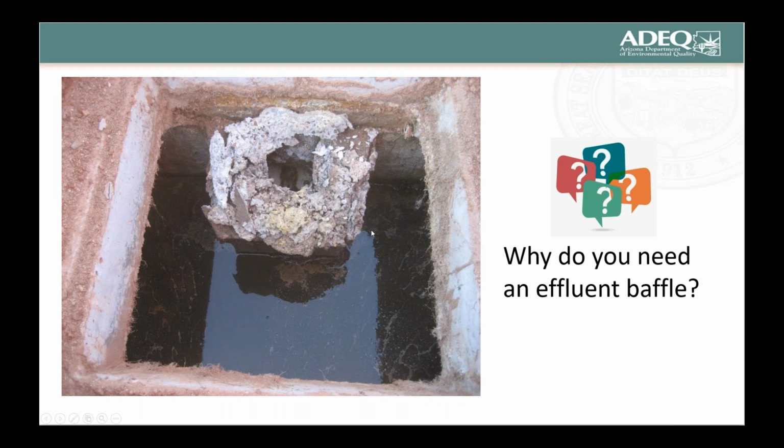All right, why do you need an effluent baffle? So here's a nice picture of a concrete effluent baffle that's being corroded and is breaking down. And so, of course, you have the baffle to keep solids out of your disposal field.